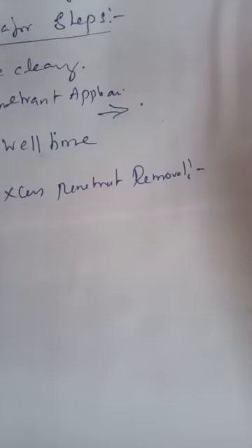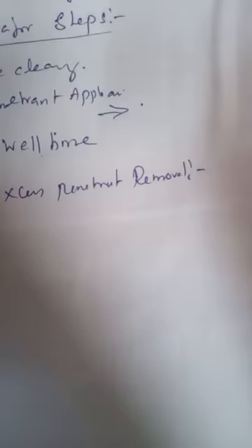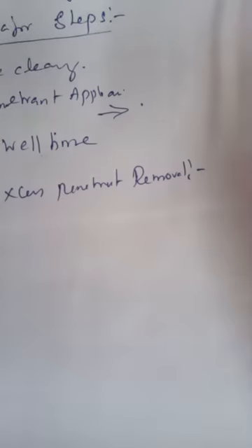The fourth one, excess penetrant removal. The surplus liquid is wiped away using a clean lint-free cloth. The technician must be careful not to wipe the penetrant out of the actual defect. Fifth one, that is developer.